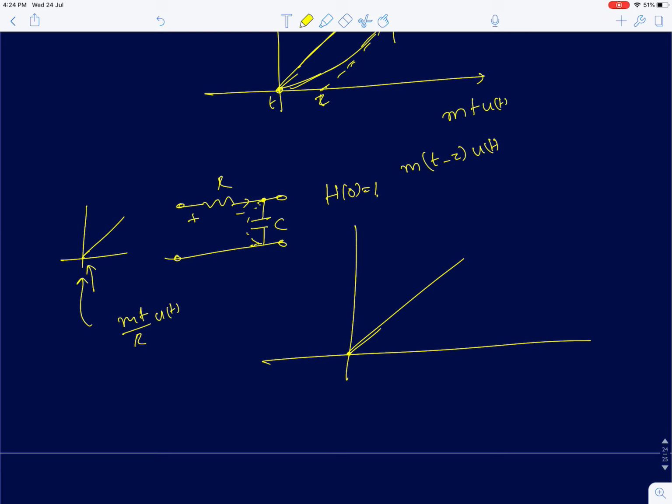At that point, this current will flow into the capacitor, and now voltage across the capacitor is integral of current. So for small values of t, the function will behave like an integrator. Okay, so the slope, if the input is raising with the slope m, the output will have zero slope because it's raising as t square, it raises as a parabolic function. So it will raise parabolically. Now we know the steady state value is actually t minus tau.